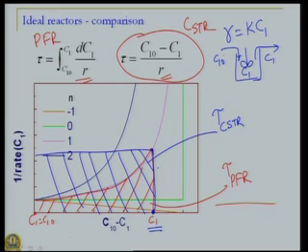In a plug flow reactor, what is happening to my concentration? My concentration is C1 0 over here at the entry point, and it is gradually decreasing to a value C1 along the length of the reactor. In a stirred tank reactor, from C1 0 to C1 is instantaneous, because as soon as the fluid element enters the reactor, it mixes uniformly with whatever is there inside the reactor, concentration drops down from C1 0 to C1. Whereas, in this particular case, concentration drops down more uniformly.